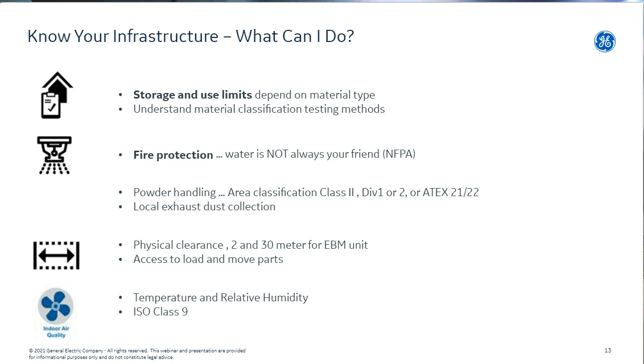Also, the machine environment maybe requires some temperature and humidity limits, so therefore you should consult your equipment manufacturer. And it could also be an idea or requirement that the machine environment is a clean room or needs to meet clean room standards, specifically when you go to smaller powder grain sizes or you have specific applications with very highly toxic substances.